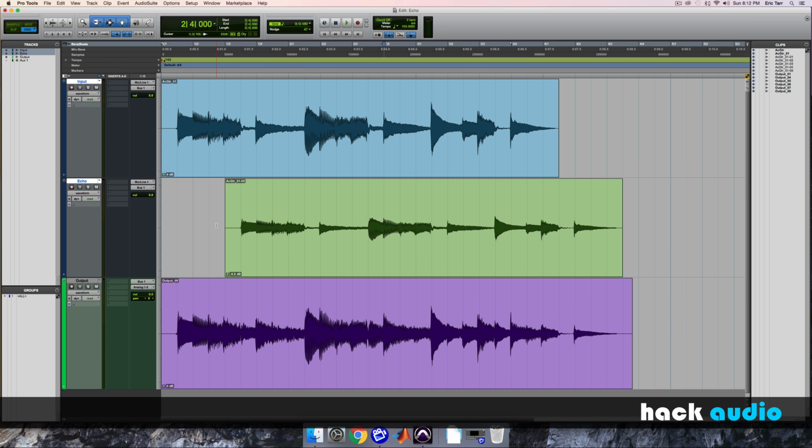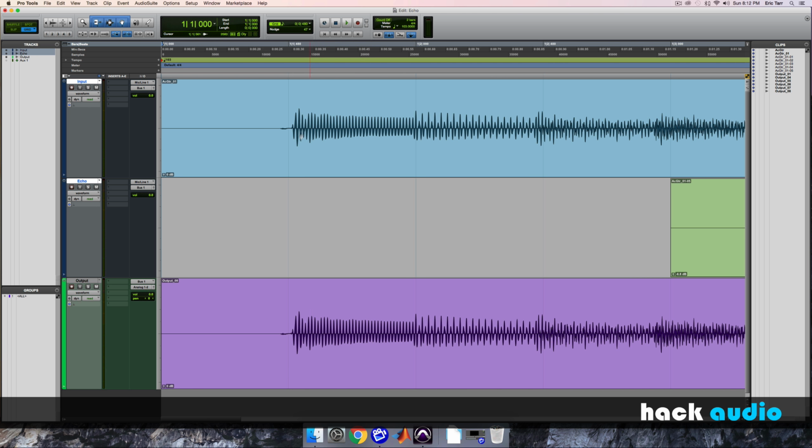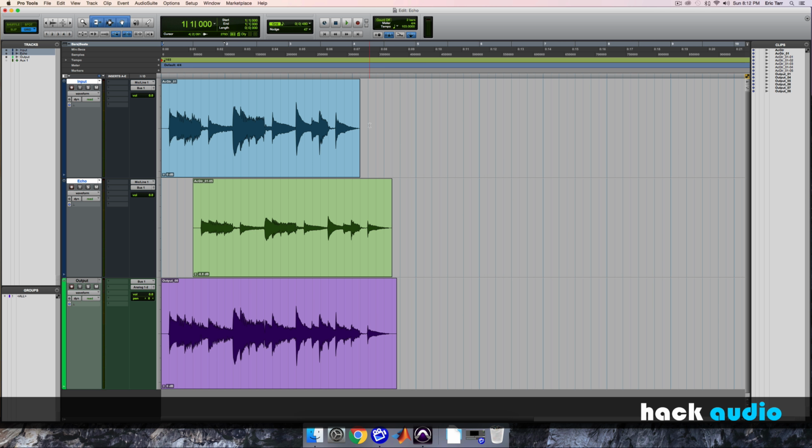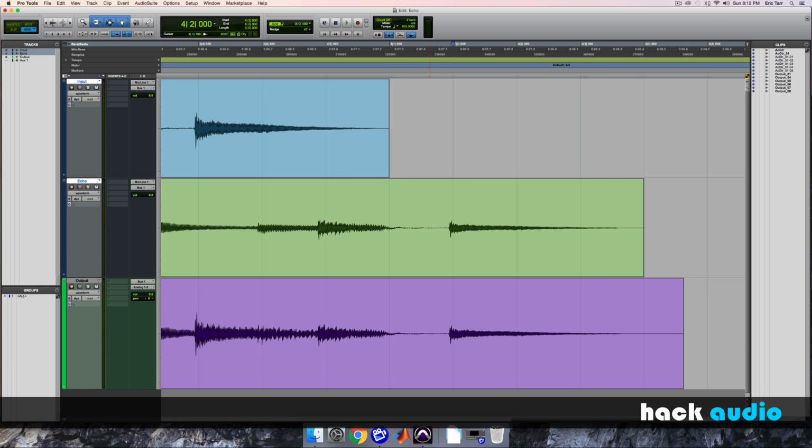Now, one thing we have to be careful about is what happens here at the beginning. Because we have amplitude up here on our input signal, but we don't have anything down here for our echo. In this case, what we can do is just add a 0 for each sample where we have something in our input, but we don't have anything in our echo. Same thing over here at the end, where we have the tail of our echo. We'll just add a 0 in up here for our input with the echo in order to create our output